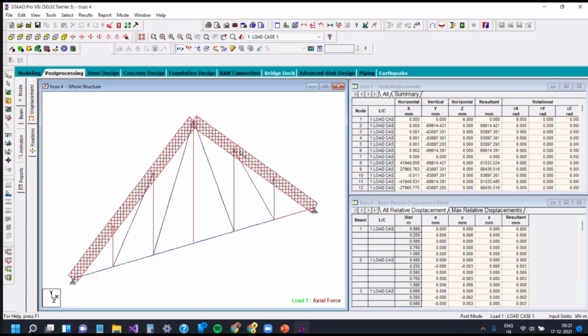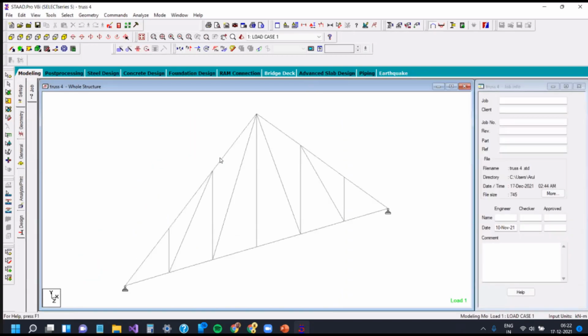Because if I have a beam with a central concentrated load, it will have a triangular bending moment diagram. Now, if I make my truss shape parallel to the bending moment diagram, it is a funicular one. So you will get the entire load dispersed through compression in the chords. One more look at this. You can see here the formation is made in terms of the bending moment diagram. Okay, excellent.